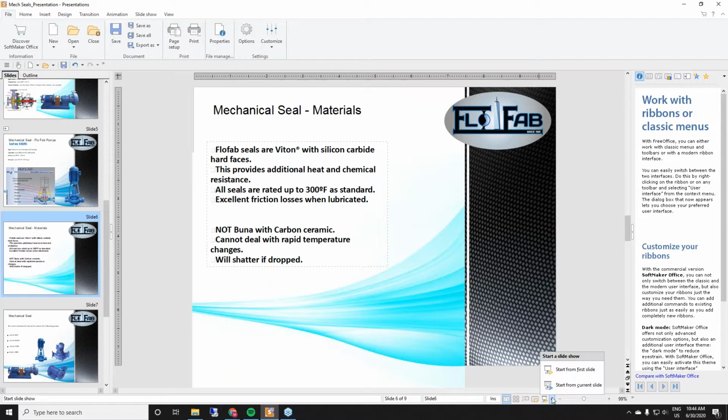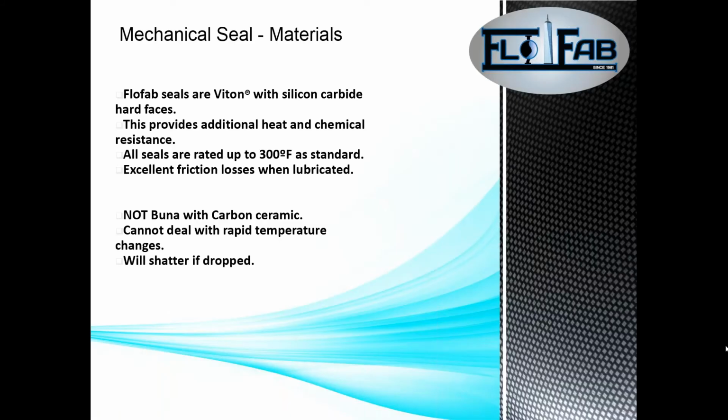Nice. So you get top quality in suction pumps or horizontal, and then you have the industry standard for the vertical inline also. Yes, that's correct. One advantage of our 880RI series is they have bearings for the pump shaft also. So the mechanical seal and the coupling are not as expensive as the competitors' pumps. So that's why we are able to use this kind of seals for the vertical inline, right?